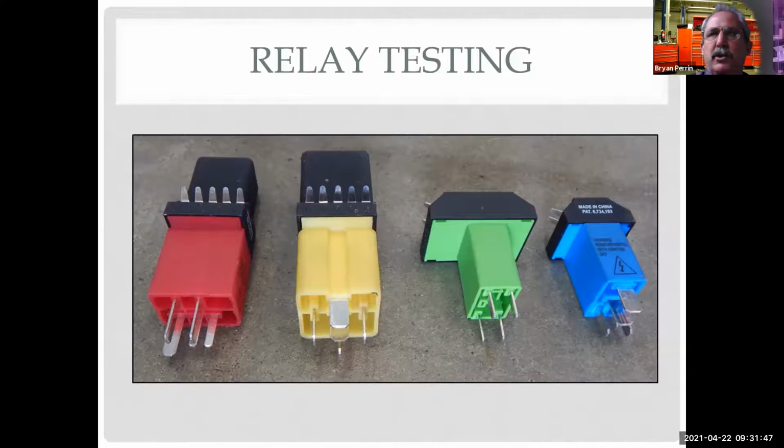If you can read a wiring schematic and have a power probe, you don't need to buy a relay tester. Relay testers are for people that have no idea how anything works, so I can put it in and have the relay tester tell me. It's not going to help you fix the circuit. It's just going to tell you, is the relay good? Well, that's only part of what I want to know. So why don't I learn how to read a schematic and use tools?